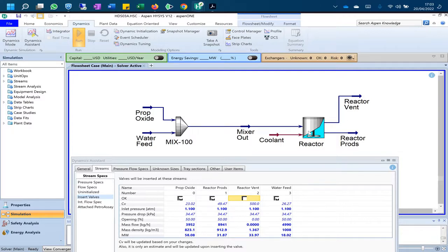When the liquid level inside of the reactor goes down, some nitrogen is required to enter inside of the vessel to maintain the pressure, because if this line is closed, when the liquid goes down, the pressure inside of the vessel will be reduced. Even the vessel structure can crash because of this reduction in pressure.